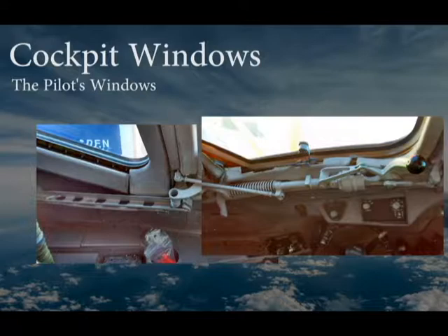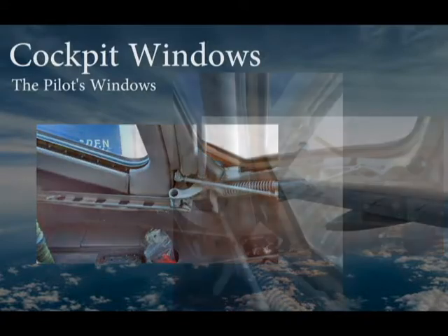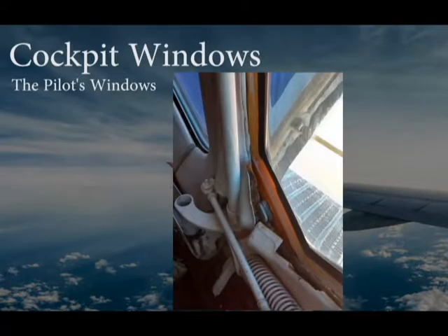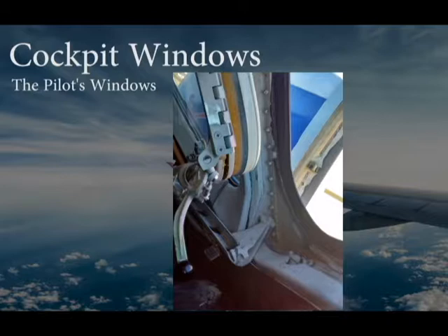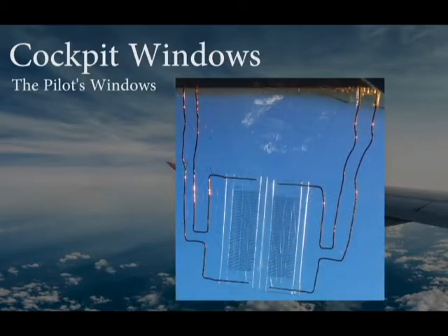The windows are a laminated multi-ply assembly, comprised of a minimum of 2 structural layers. These structural layers are typically made from strengthened glass, either by methods of thermal or chemical means, or polymers such as acrylic and polycarbonate. Apart from the structural layers, the cockpit windows include the protective facing plies to help mitigate the effect of scratches from use. The final components of note in the cockpit windows are the electroconductive wires. These wires are used as a heat source to prevent the windows from icing over and thereby preventing obstruction of the pilot's view.